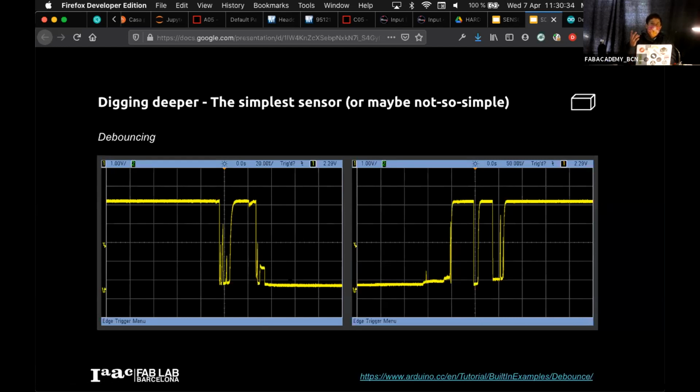This happens many times, for instance, when you are developing in your machines, and you press a button and it starts triggering things too soon, or it never triggers things. It might be for this reason. So just plotting what happens when you press the button might help as well. Basically it is a very simple trick to understand whenever there's a transition or not, and just wait a little period of time to measure it. Yeah.